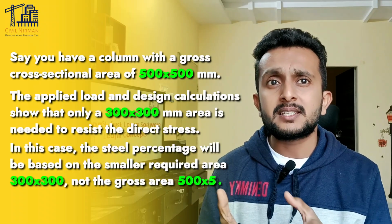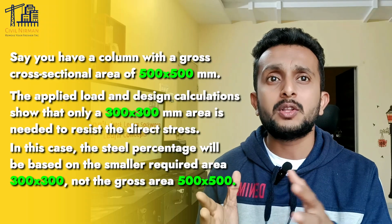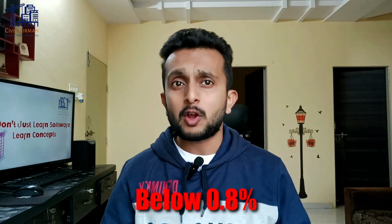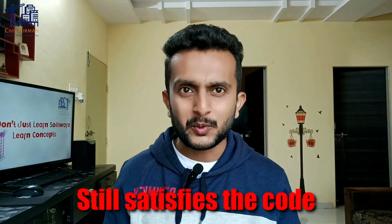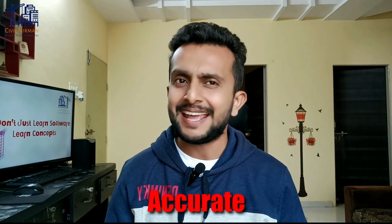stress. So in this case, the steel percentage will be based on the smaller required area and not on the gross section area. So if STAAD designs the reinforcement based on this required area, the percentage can indeed fall below 0.8% of the gross area but still satisfy the code. This feature ensures material optimization without compromising safety or code compliance. So STAAD considers the exceptions in IS 456 to produce designs that are both efficient and accurate.